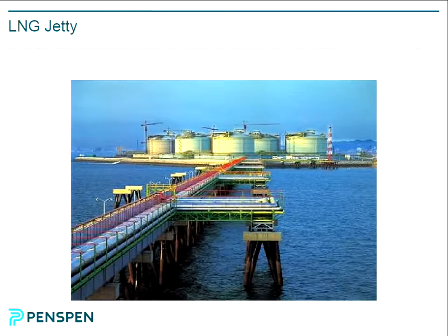You'll find that conventional carbon steel is not tough at that temperature, so you end up using expensive nickel-based alloys that maintain their properties at these very low temperatures. So you store it in insulated containers, you transport it in insulated containers. These are insulated tanks, and this is the loading jetty. So this is an LNG pipeline. They are very rarely subsea. There are some examples of subsea LNG pipelines, and sometimes they are onshore.